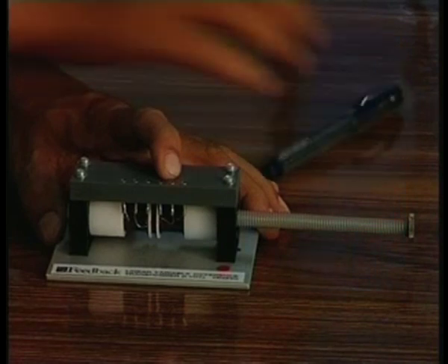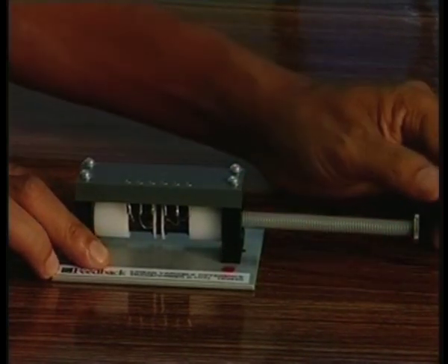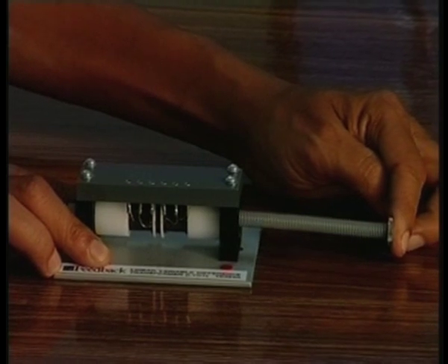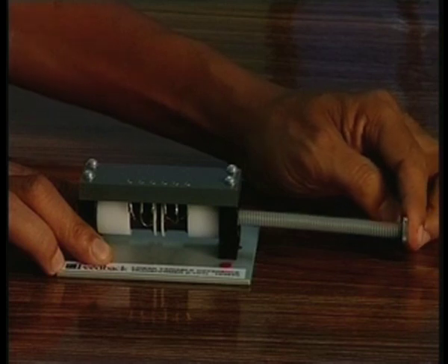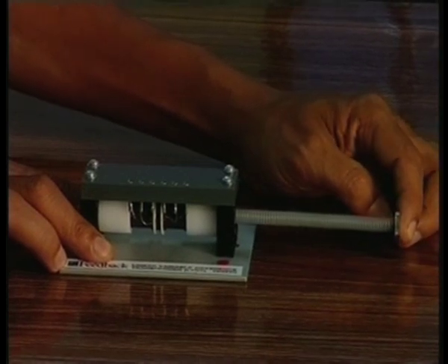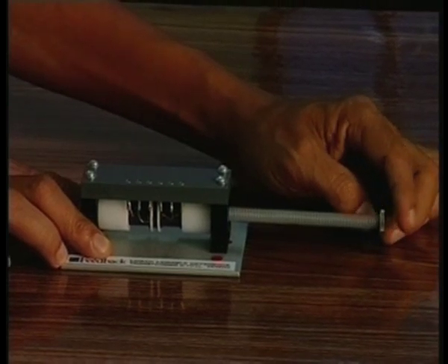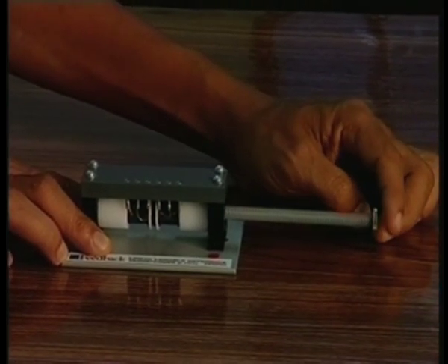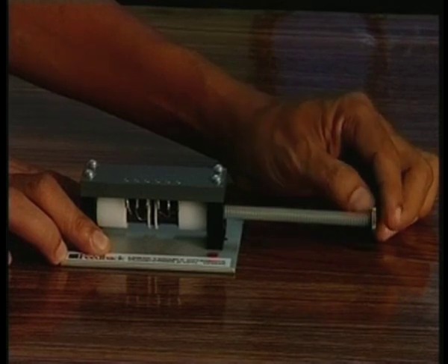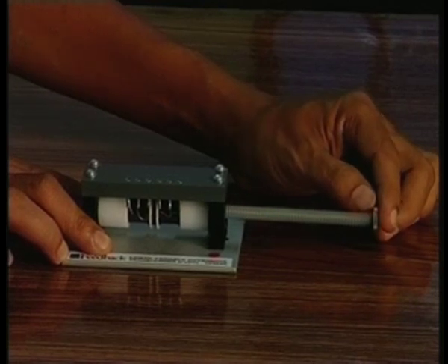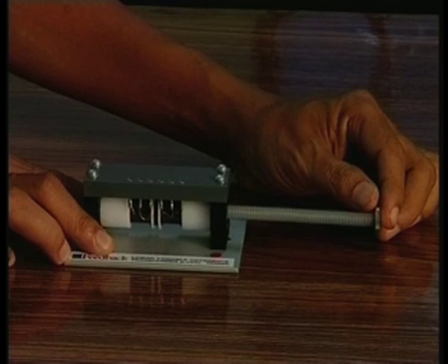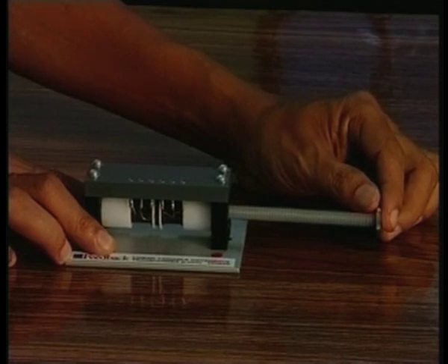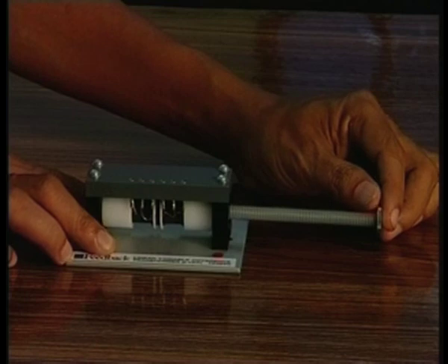You see here the core is there, a soft iron core, which will move like this. So now I am moving it, it will move like this. And since there are two secondaries, what will happen if you put them in opposition? Obviously, you will get some output voltage, and when it is exactly at the null position, the two secondary coils' output voltages will be nullified, and I will get 0 voltage. But any position other than that will give you a non-zero output voltage. So LVDT we have already discussed in detail. So this is actually a pictorial view of the LVDT.